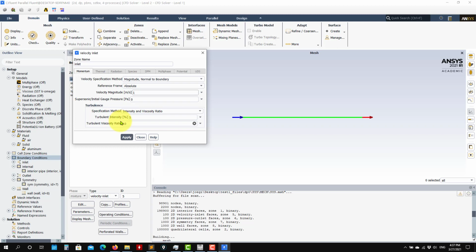And then see here that you need to give boundary conditions for the turbulence model. So we saw this in the theory. In this case, I will choose intensity. So I will put, let's say, 1% intensity, and this one I know is 0.01. Apply. And you are all set. These tabs here are related to models. So if you put compressible flow or temperature, you will have those. For the moment, we don't need those options.